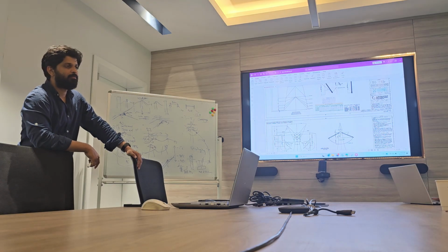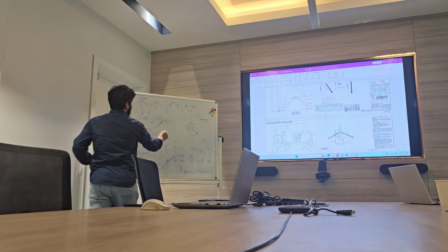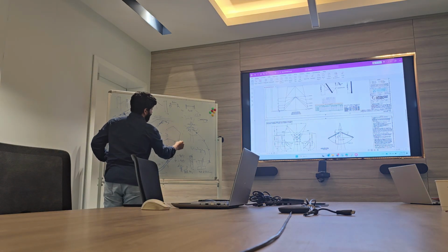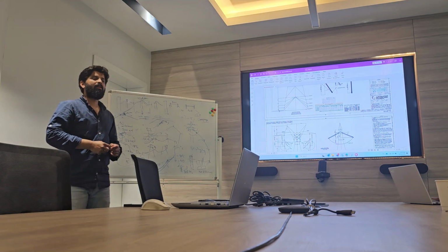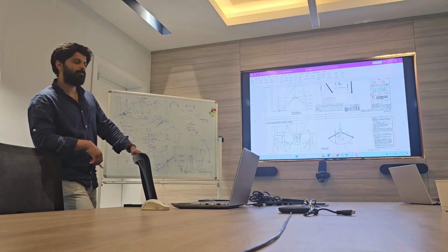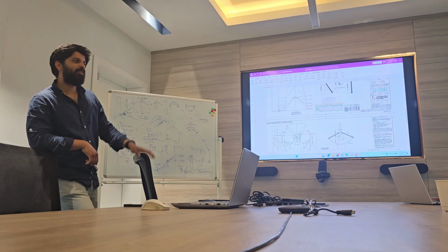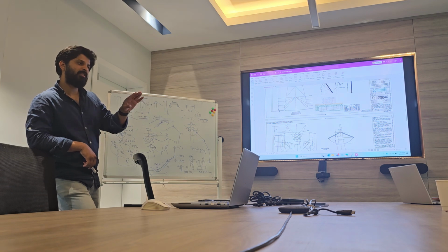Okay. So why do we use this between certain distances, if we are going in a very long straight line? We're suspending the line, but as you said, for anti-cascading, we need to use this tower at 0 degrees, for example. 0 whatever degree, 90. Even if you have a line like this, suppose you put a dead end tower here, you don't need to put another for 12 kilometers. After the tower, it will also be connected from both sides, right? We continue again. That's the specialty of a dead end tower. You connect it from both sides, it will work. You connect it from one side, it will work.